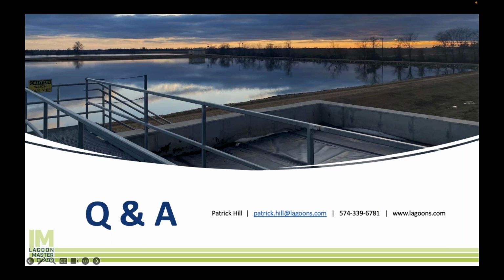What might cause a spike in effluent ammonia when other parameters remain normal? It's typically benthic feedback. If you watch my biosolids webinar, it's the solids in the sludge. One classic ammonia spike would be if you grow duckweed on your lagoon.